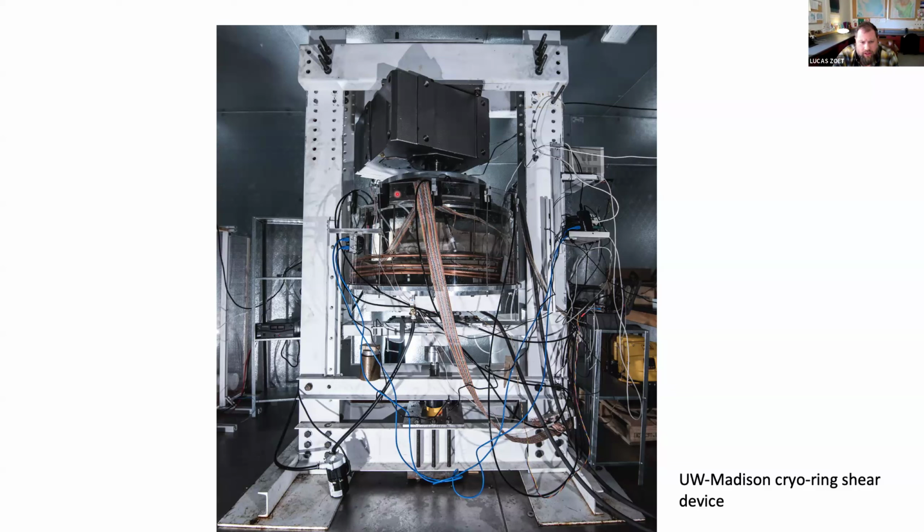And you can see there's all sorts of cables and wires coming out of this thing. We measure a lot of different properties, things like the water pressure, the temperature at many different points. We have these cameras that can look through the sample chamber into the ice and monitor it. This whole sample chamber is actually sitting inside of a big tub of antifreeze right here, and that antifreeze helps us regulate the ice temperature to within 1/100th of a degree.